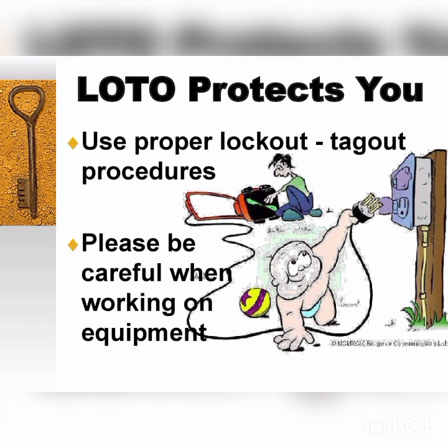Whenever you are working on the equipment and have to do a maintenance job, make sure, as I told you before, that all the sources are disconnected. And when you are going to start up, make sure all the areas are restored. In this picture, it is mentioned: jaw crusher turned off, no locks on the side, a person is inside. Say for example another person comes and switches on the equipment, the jaw crusher will start, and the person inside will be crushed.